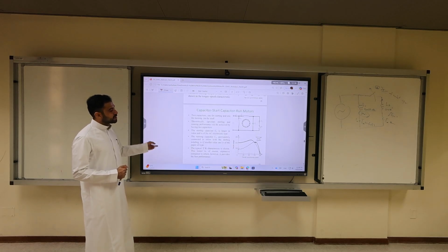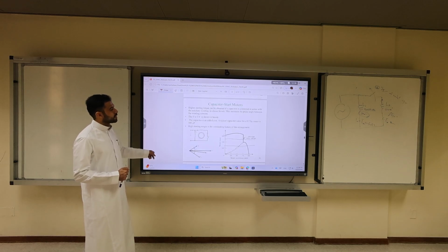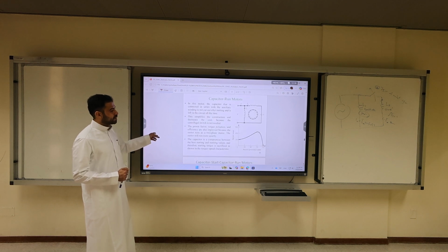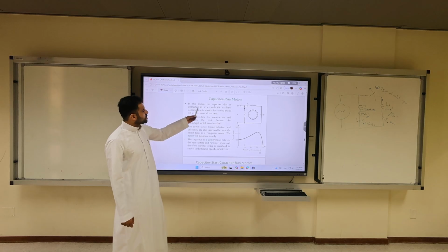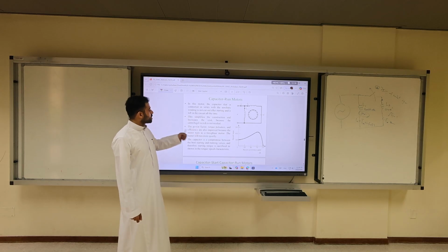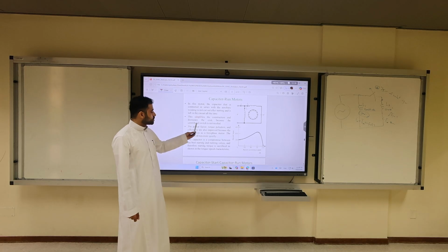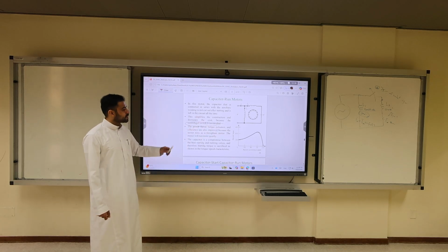So we have capacitor run. That's another type. So what do we have here? We have capacitor start. Capacitor run, it's your idea. Capacitor that's connected in series with the auxiliary winding is not cut after starting. Keep it. And left in the circuit all the time. This simplifies the construction and decreases the cost because the centrifugal switch is not needed. We don't have this 75%.